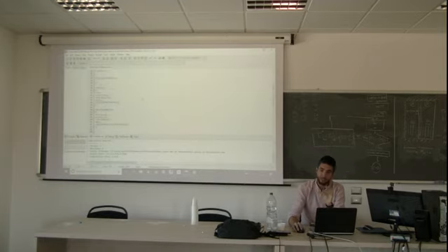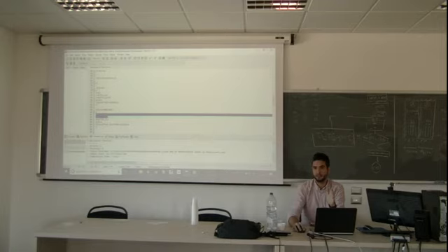And if this value is very, very low, keep in mind that in the equations this value is in the denominator, so you can have numerical problems. That's why sometimes the solution is to add more nodes. But sometimes no. Sometimes you have to be realistic. Adding more and more nodes is not necessarily better, because you are having tiny numbers in the denominator. If there is a truncation error or something like that, then everything will crash.